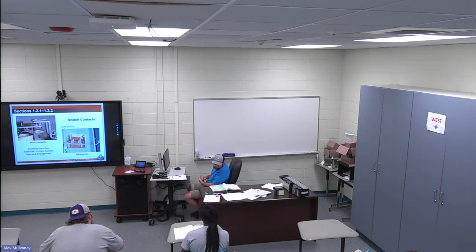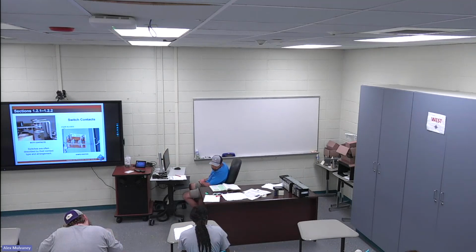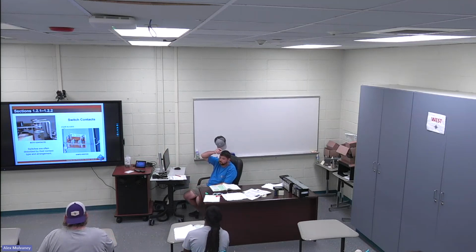Skip a sentence, and I got the last two sentences in that paragraph highlighted. Standard electrical switches should not be used to interrupt a circuit that is subject to short circuit or overload conditions. Fuses or circuit breakers are designed to prevent such conditions. That's why you don't have light switches turning on motors and stuff like that. Or at least you shouldn't, that don't have any overload protection or anything like that.